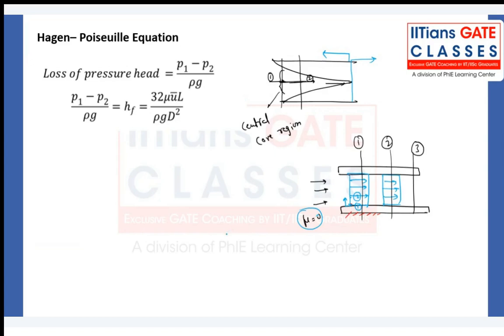See how you can justify there also in a central line. At section 1 and section 2 in a developing region, here velocity is less, here velocity is more. Velocity is less, velocity is more, but pressure is more, pressure is less. So both the terms, kinetic energy and pressure energy, sum together in such a way that total energy remains constant. Although the potential energy will not vary, as points 1 and 2 are on the same line. Getting my point? Yes or no? So this thing has been clear.